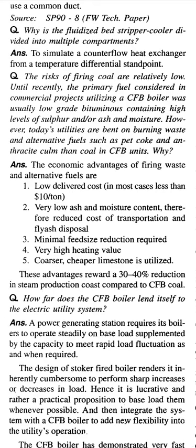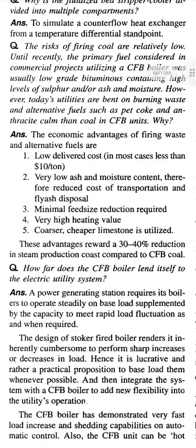Very low ash and moisture content, therefore reduced cost of transportation and fly ash disposal. Minimum feed size reduction required, very high heating value, coarser, cheaper limestone is utilized. These advantages reward a 30 to 40% reduction in steam production cost compared to CFB coal.